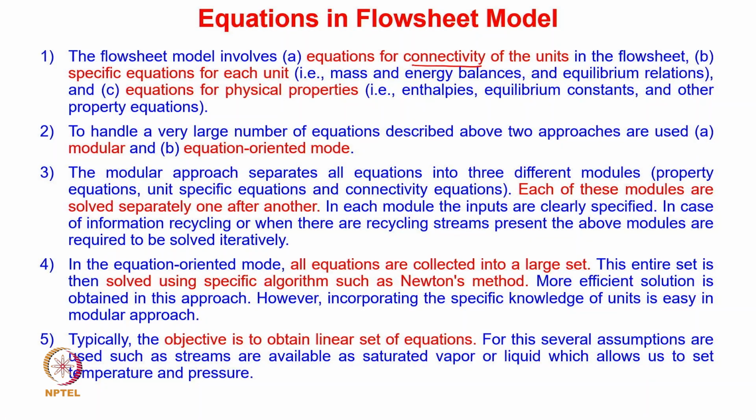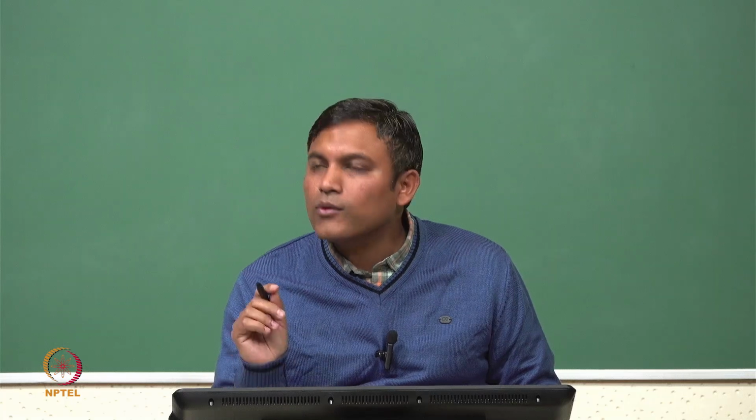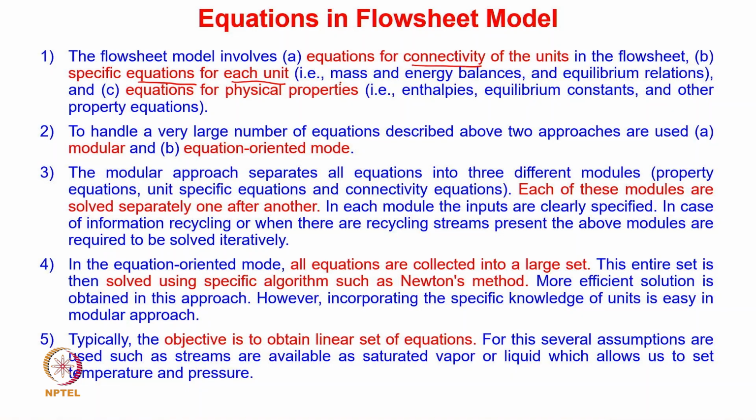The next class of equations are the specific equations for each unit. These are the mass and energy balance and equilibrium relations with respect to a particular equipment. So how the input and output of a particular equipment or unit are related with each other, how the physical changes are taking place, all of those are described using mass, energy and equilibrium relations, and these are referred to as unit specific equations.